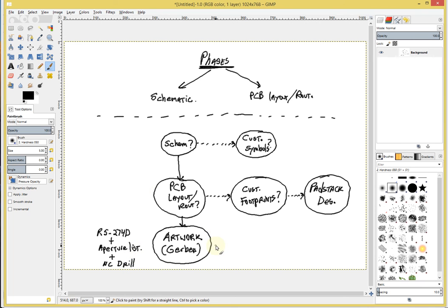Okay. The modern version of this, the standard today, is basically RS-274X. Basically, this file takes the aperture list and embeds it into the file, so you only provide one set of files and you don't need a separate aperture list. So you would provide a manufacturer just with your artwork files for all your layers, and then a separate NC drill file. And your manufacturer proceeds from this to produce your actual PCB board. And that's what you get in the mail once you wait for it for approximately 2 weeks.